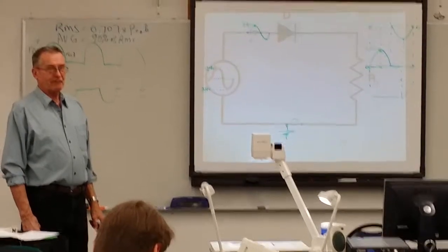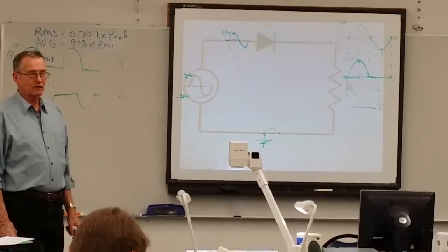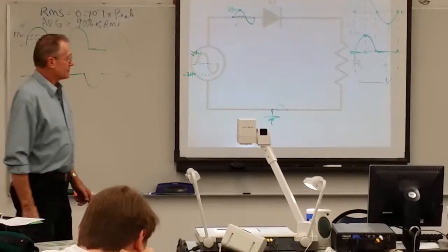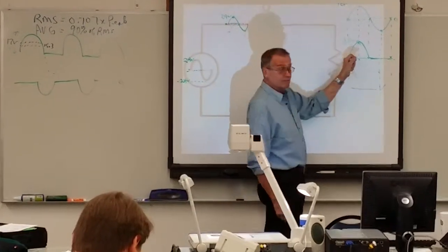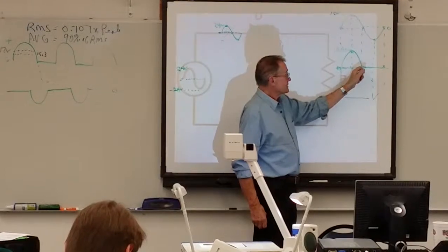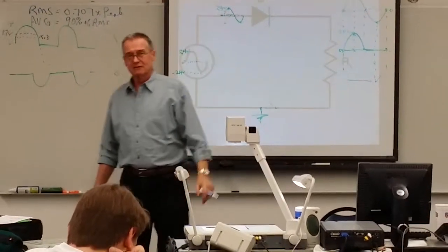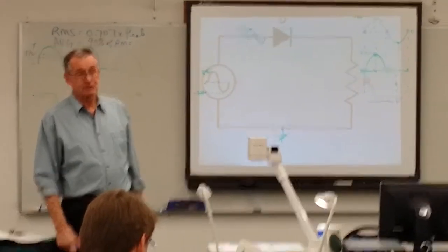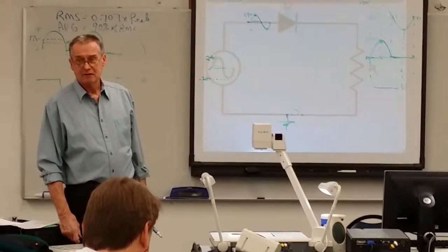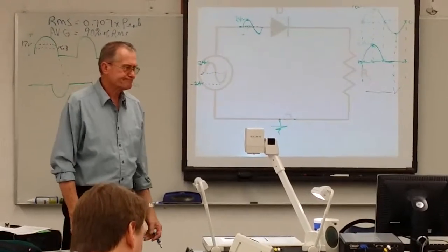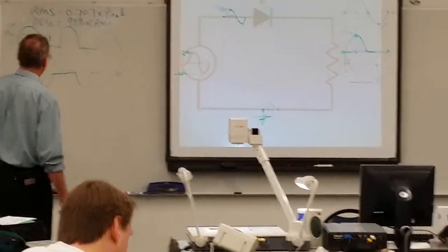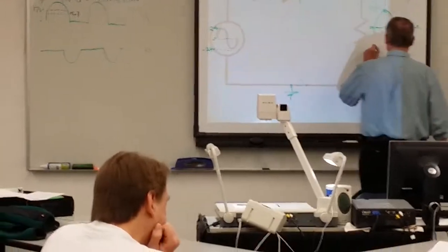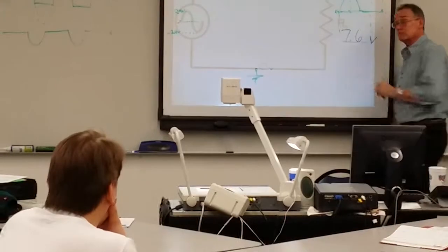The other thing you wrote in your notes last week, at least if you did what I told you, it would say that when you read average, it reads the average for one complete cycle. And the average for during this time is 15.3. But since it's 0 half the time, we have to divide that by 2. Which is 7.65 or something? Yeah, 7.635. About, what'd you say it is? 7.6. Yeah. So what you're gonna get out of here is about 7.6 volts, isn't it?